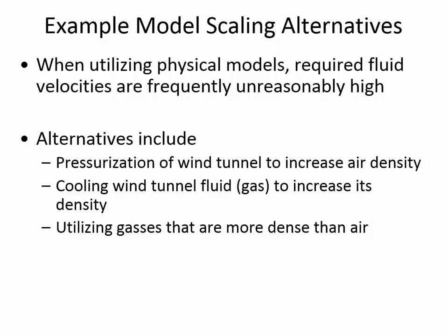And we could find out with water that has a higher density and a different viscosity, we could find out how the air is going to affect the prototype by using a non-air liquid for the model. So you can change things around, and sometimes in simulations they'll use different fluids just because it becomes easier for them to take the measurements that they need. Any questions so far about what we're talking about here? Similitude?